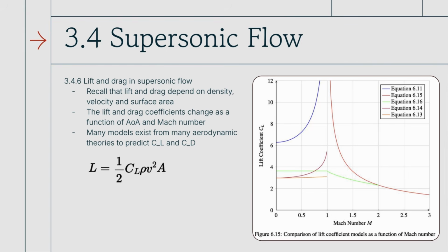This lift or drag coefficient is going to, one, account for angle of attack. So often in textbooks, you'll see the coefficient of lift is 2 pi times the angle of attack. That helps quantify how much lift you're actually producing if you have a more angled airfoil relative to the flow. It also is a function of Mach number typically.